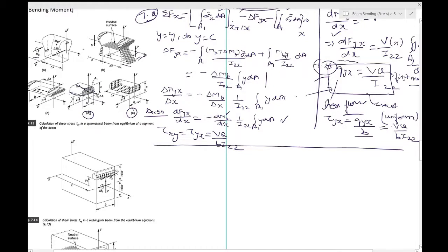Okay, so let's see it under slightly more specialized conditions, and that is when you have a rectangular beam or rectangular system. Okay, so this is theoretically another way to find the shear force distribution, and what you have studied until now was the general method. This is the specialized method. Okay, so in case you have a rectangular beam, you can use this method which we are about to discuss now, but the above method will work for any cross section as long as they satisfy the conditions which were required. Okay,